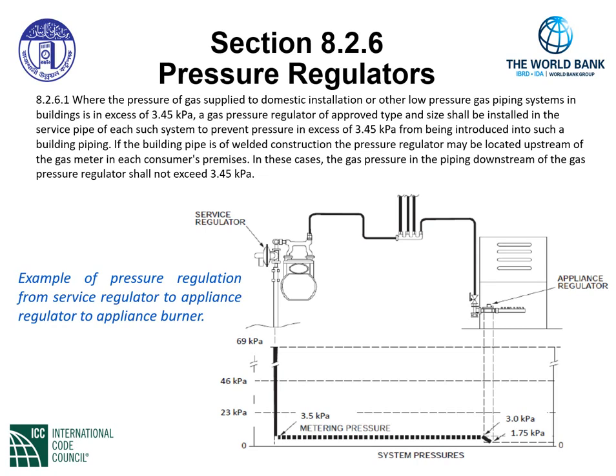Please look at the underground piping emerging from the earth. It actually will go into the inlet of the service regulator. What you don't see here is the service valve that will be located below the service regulator. So the piping coming in from the supplier will enter the inlet of the service regulator.